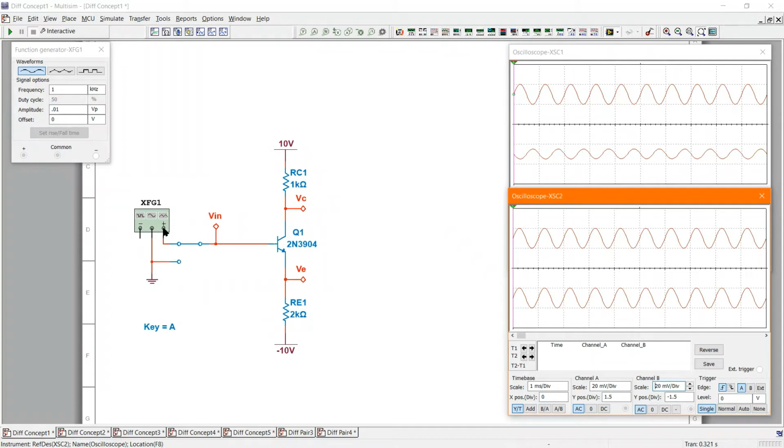So if I take that 600 ohms and divide it by beta, because I'm looking back through the emitter, and beta is 100, you're looking at an output impedance on the emitter of less than 10 ohms. So it's a pretty low output impedance. Now this can actually be connected to and can drive something as a low impedance source.